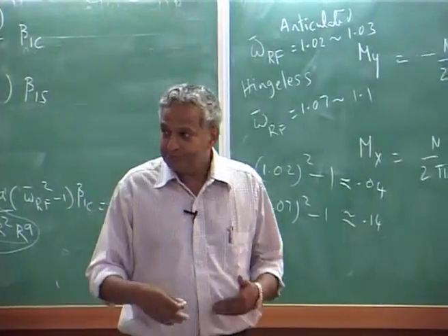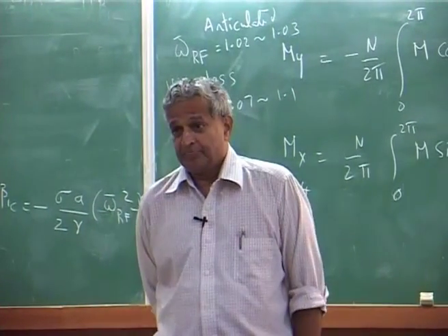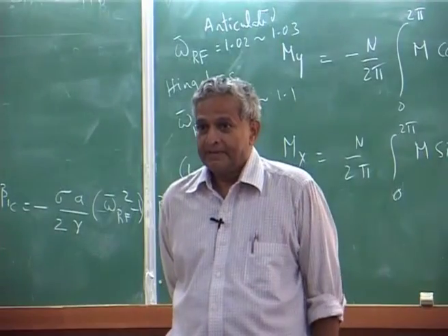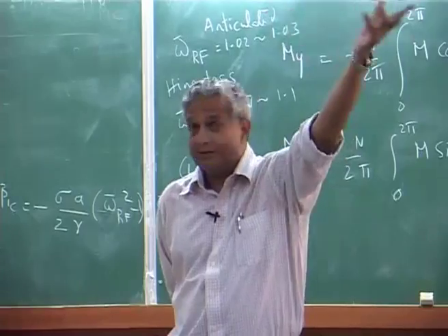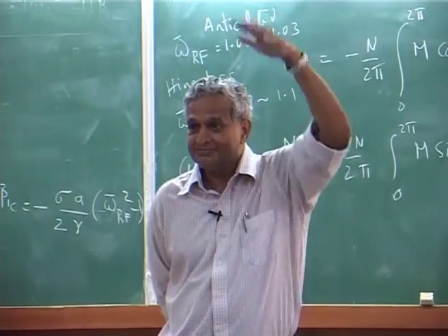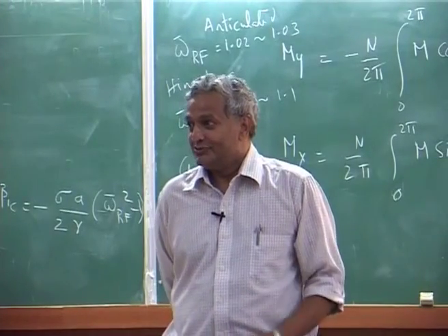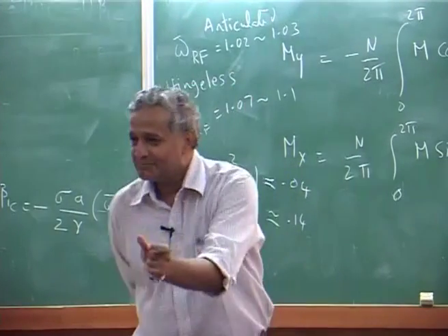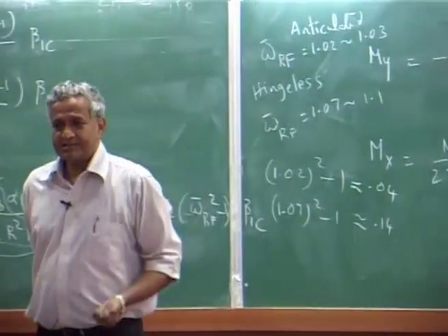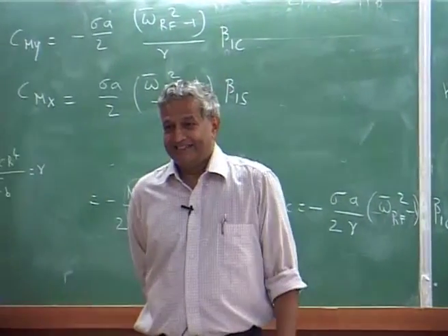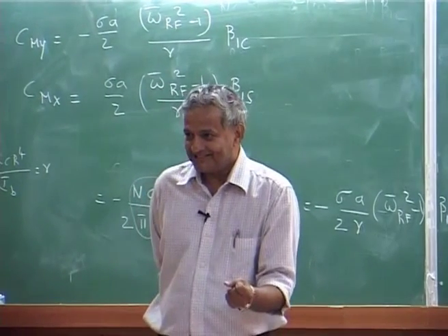Now you find that when I have my flap frequency high, I get a good control moment, but at the same time that means I am transferring a lot of loads from the rotor to my fuselage. So, I will transfer more vibration also. If you have a small flap frequency, the load transfer is less, vibration also may be less, but control is also less, agility is less.